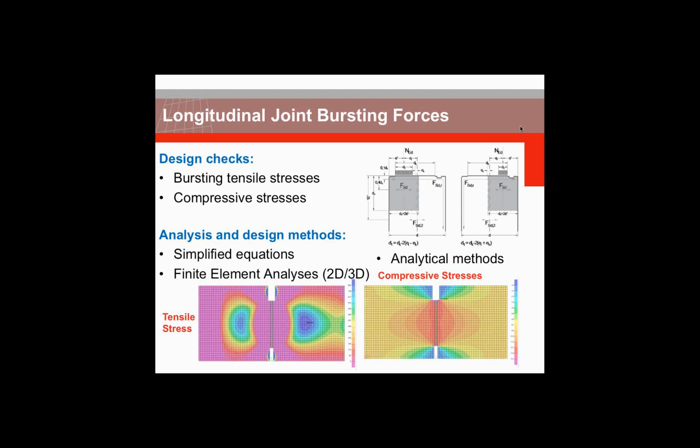Because we're focusing our attention only on the longitudinal joints, it's good to get these axial forces and bending moments from the results of models such as beam springs. And the bending moment is basically analogous to eccentricity, if we consider that the ratio of the bending moment over axial load is the eccentricity that can be applied.